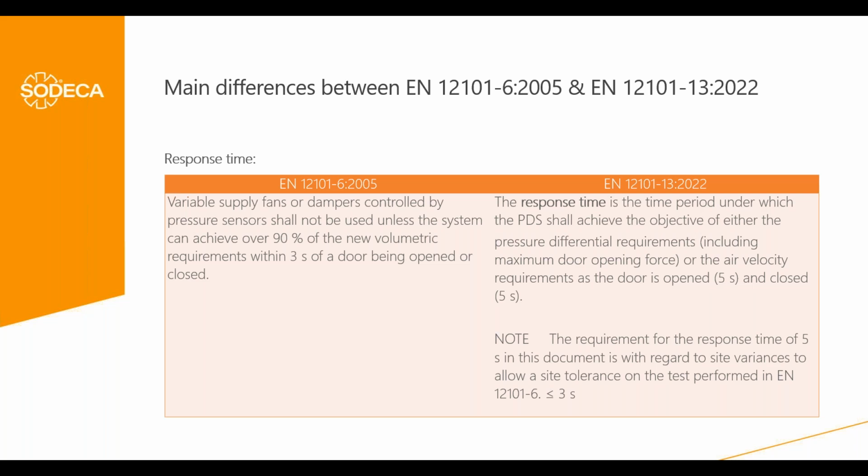So the airflow in the door open condition was typically the maximum one, the 100, the nominal flow of the system. So it was clear in the door open condition that we need to provide 90% in less than 3 seconds and arrive to 10% a little later. Okay. But when we close the door, it's not clear.